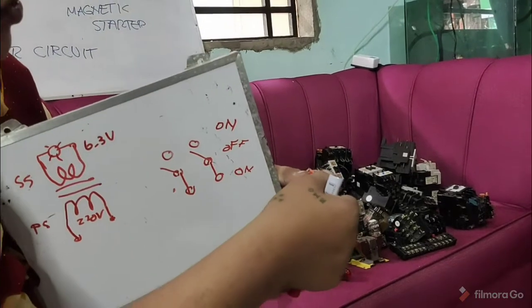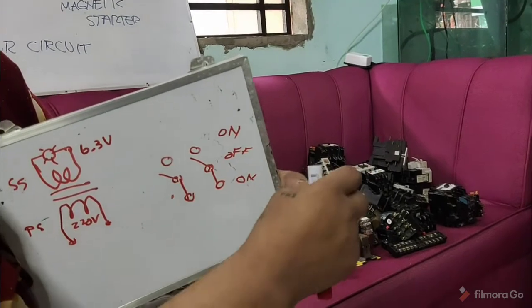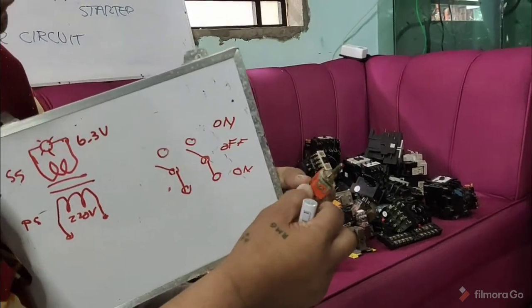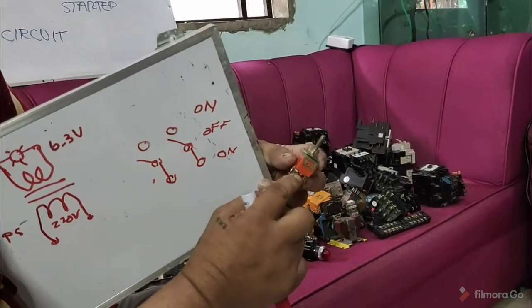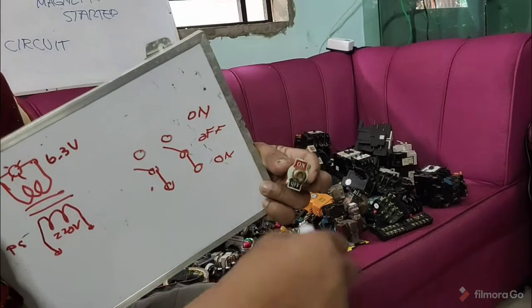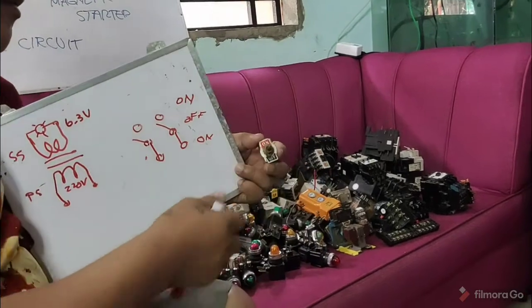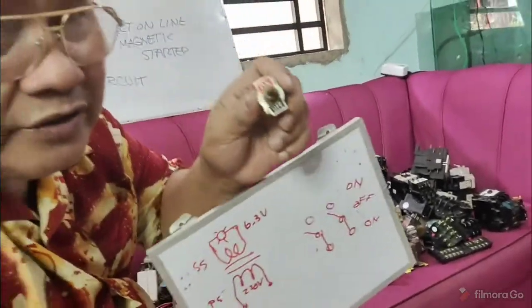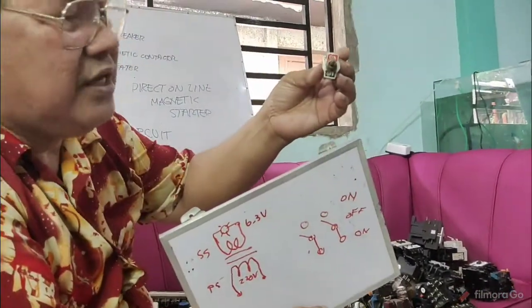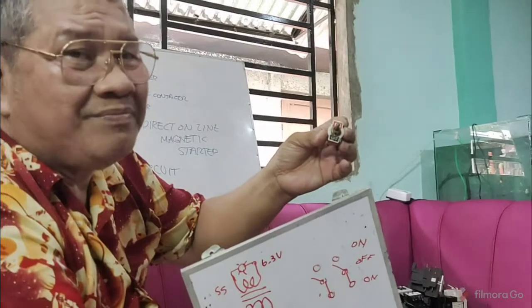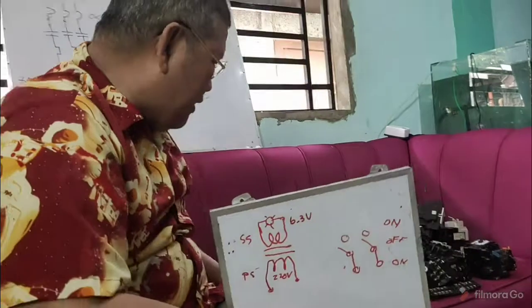It does not mean that when you switch on, the contact in the upper portion is being contacted. So when you switch on, again, I will emphasize it, it is the contact below, and when you switch down, it is the contact in the upper portion. Okay? So that is the principle of the toggle switch. Now, we can use this instead of the selector switch like this, you can also use this as your selector switch.